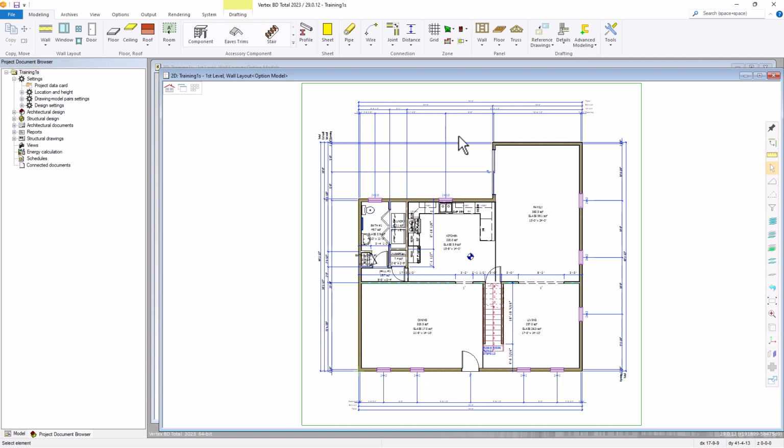Now that we have our wall framing settings assigned, we can proceed with panelizing our first level walls. The wall panel tools are located under the Modeling tab, Panel, Wall tool. We will cover the basic wall panel tools, like the Panel Break macro, the Generate Panels and Generate Parts programs. We will also add some additional macros found under the Wall Panel Layout Accessories library.